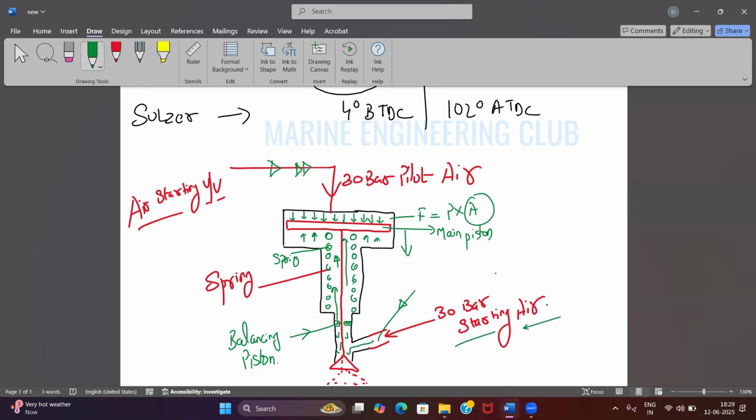Okay. Now you might have seen this is a very big line, the starting air line that comes. Agreed? But this is a very small diameter pipeline, maybe a diameter of 2 fingers and all. It is only for actuating purpose, for which unit air will be given. For ME engines there will be one solenoid valve. In a conventional engine, this air is coming from the distributor.